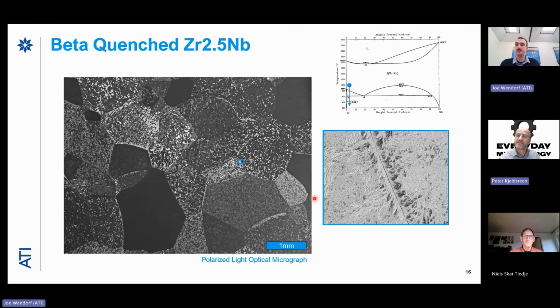Small nanoparticles. And there's a lot of detail that I'm still trying to understand about how the niobium comes out, and does it form this kind of 19% niobium beta phase, or does it go all the way to the 90%? It depends on how you age it after extrusion, how much deformation you have during extrusion. It gets very complicated after this step.